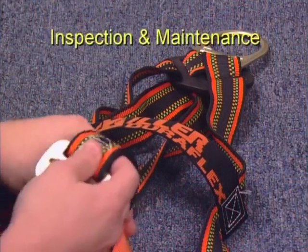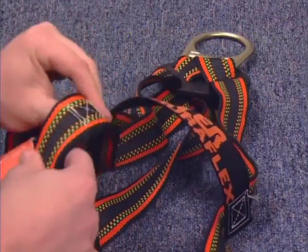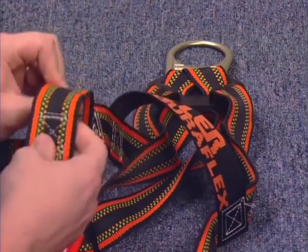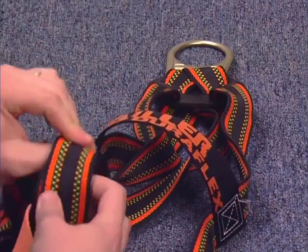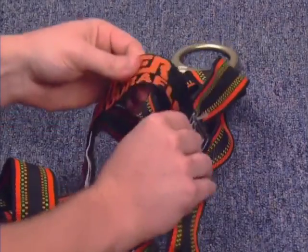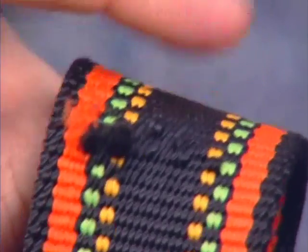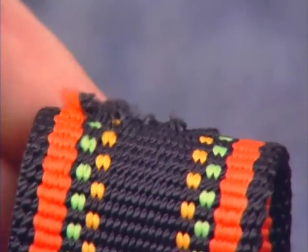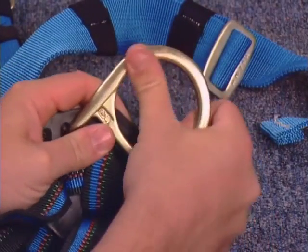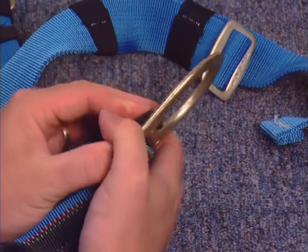To begin inspection, grasp the harness webbing with your hands 6 to 8 inches apart. Bend the webbing in an inverted U as shown. The surface tension resulting makes damaged fibers or cuts easier to see. Follow this procedure the entire length of the webbing, inspecting both sides of each strap. Watch for frayed edges, broken fibers, pulled stitches, cuts, burns, and chemical damage. Check the D-rings and associated metal parts for damaging corrosion, distortion, cracks, breaks, and rough or sharp edges.